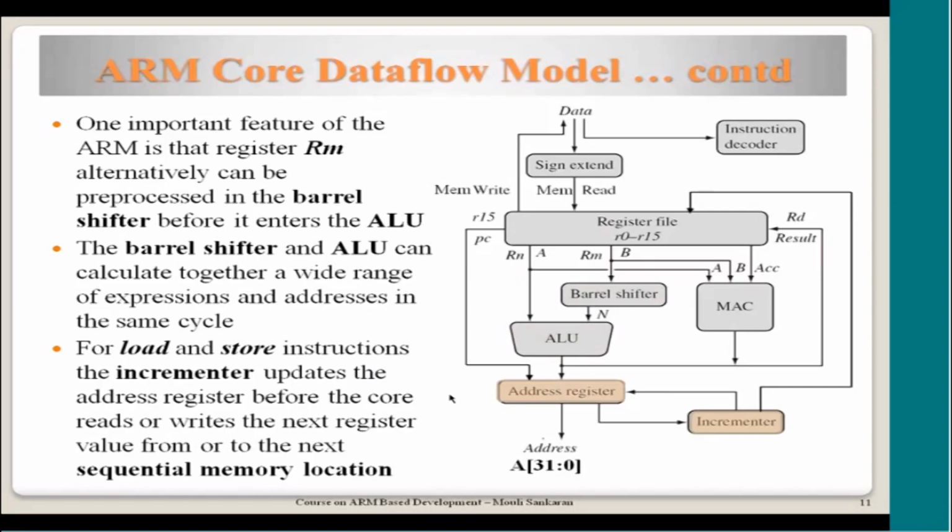And for load store, as I mentioned, in the memory there are non-sequential access and sequential access. Sequential access means in the sequential access cycle, multiple address data locations are either read or written in the memory by one single instruction.